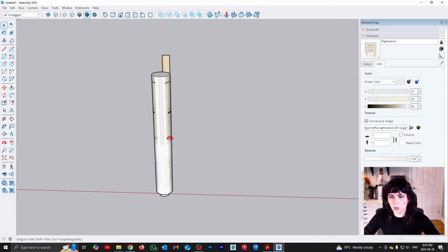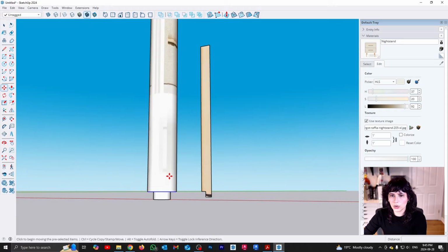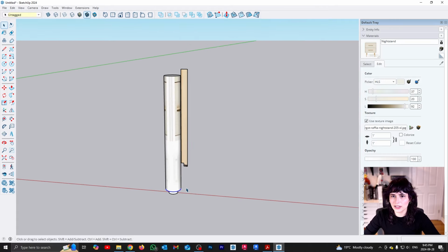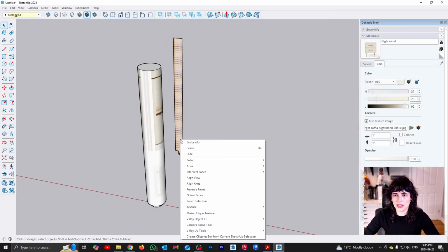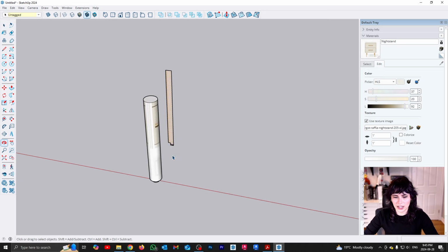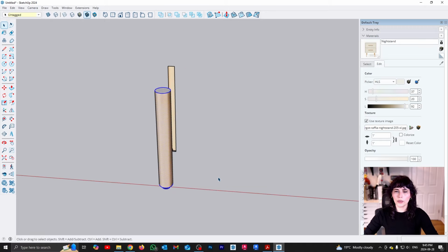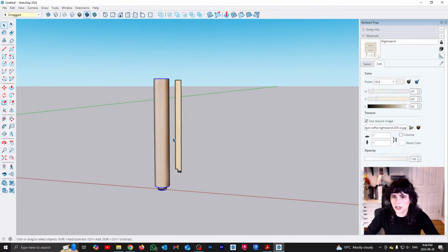Now, this is why I created a copy of the leg, because you can see that the material is all messed up, and I'm going to fix this by making this into a projected texture and then applying it to this shape. This is why I saved this copy aside. So I'm going to select this guy and apply. And this is also why when I was drawing it, I drew it a little bit in. Because if you use a projected texture and you are seeing a little bit of the background, then on the sides, it would look white. Okay, there you go. That's looking much nicer.